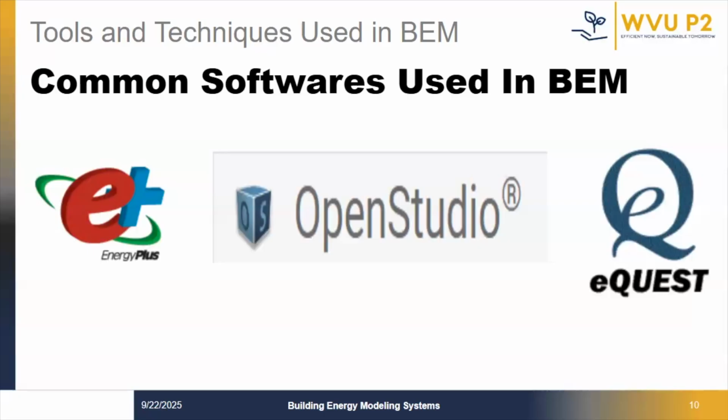The third software is eQuest, which is a free building energy simulation tool which has a built-in wizard-based interface, which is designed for ease of use. This uses the DOE-2 simulation engine. The combination of OpenStudio and EnergyPlus is a more modern, flexible, and detailed simulation platform where OpenStudio provides the interface and EnergyPlus is used to run the simulation.